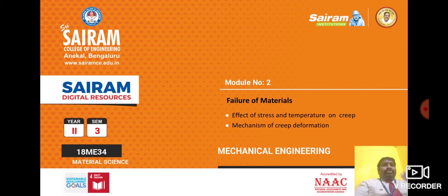For the rupture time, or time to failure, this is the time required for failure of the material to occur at a known time, which we call the rupture time. This rupture time is another important parameter, especially in short life creep situations such as turbine blades, in power plants, military aircraft blades, and rocket motor nozzles. These all come under the rupture time.